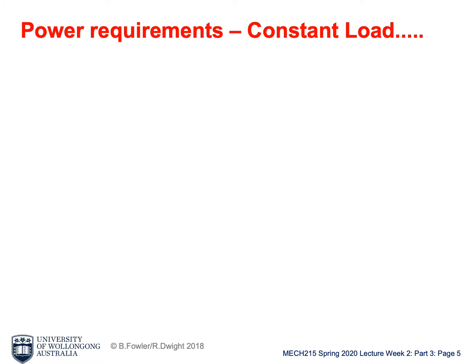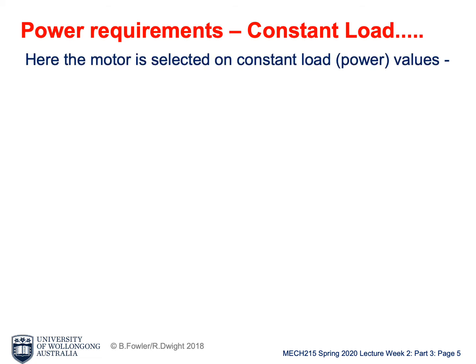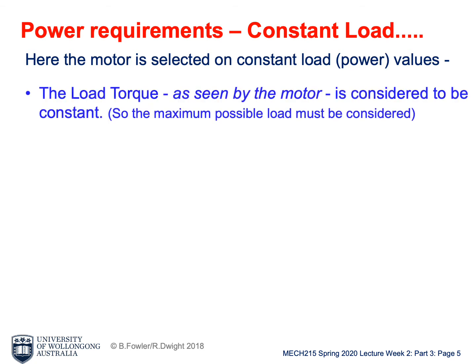Power requirements are the most important calculation we need to do for the selection of a certain motor to drive a certain load. For our conveyor, we can consider it a constant load, meaning the load doesn't change from the static motor condition to the normal running or full load condition. The torque and the load speed normally are on the output side.